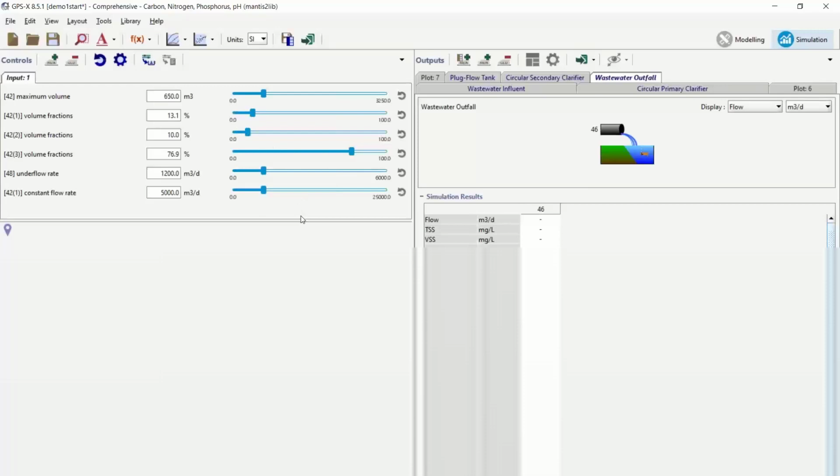Like our nitrate is 8, so we're actually doing pretty decent denitrification, or not bad anyway. I mean, it was like 30 coming in, so that's pretty good. And the most important one, though, is our BioP, right? So here's soluble phosphorus, 1.13. So that's okay-ish. And let's see if we can improve upon that.